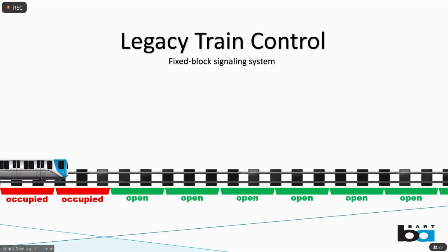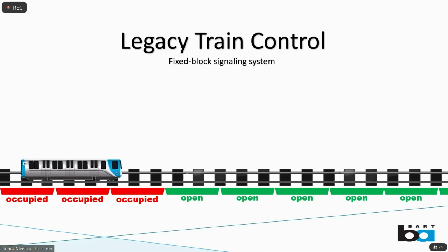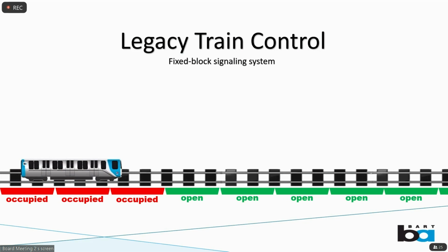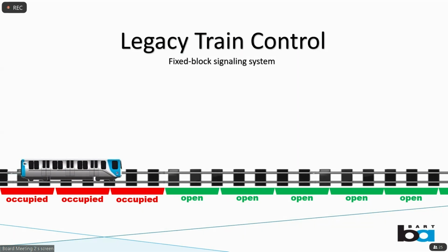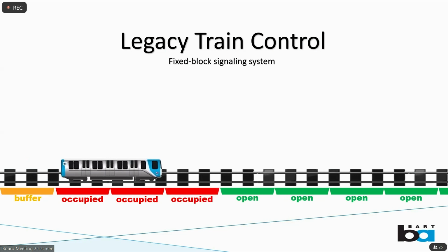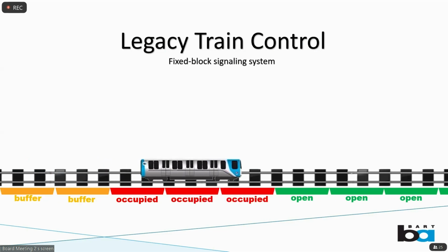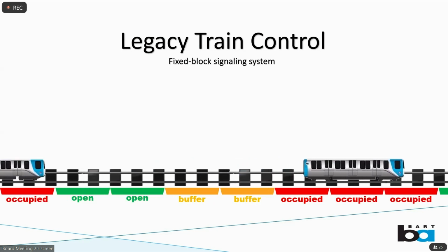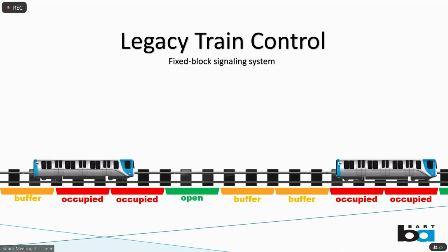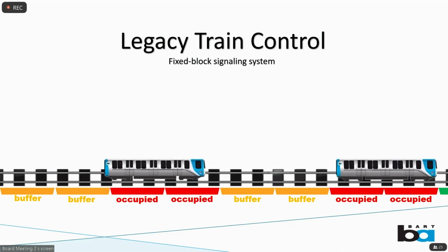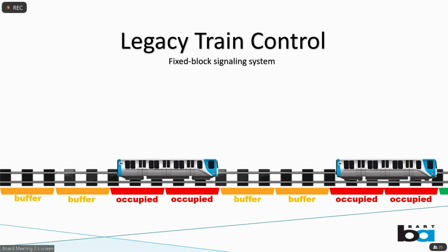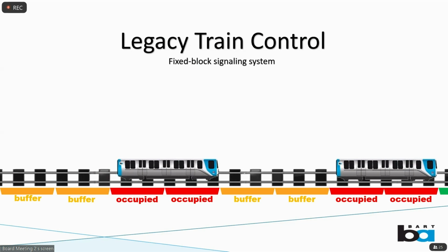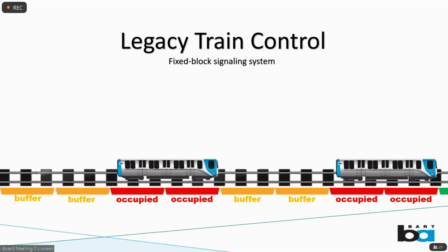Okay, to understand the future CBTC system and its benefits, let's walk through how the current train control system works. It's made up of a series of blocks along the trackway. This is showing a train moving across the track. The track circuits are organized into fixed blocks, and they're adhered to the track. They're anywhere between 50 and 1,200 feet long, and typically a 10-car train covers approximately 2 blocks as shown in this animation.